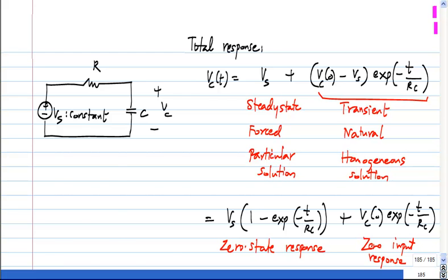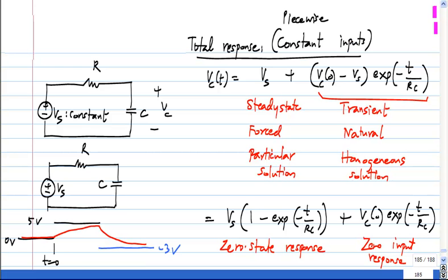response. So you can think of these two expressions as here where you have the steady state solution, but there is some residue, which is the difference between initial and steady state. That part decays with time. Or this also is illuminating, in that this you can think of as the source voltage building up to its final value, that is this 1 minus exponential, and the initial condition decaying off. So that's the interpretation of these parts of the solution.